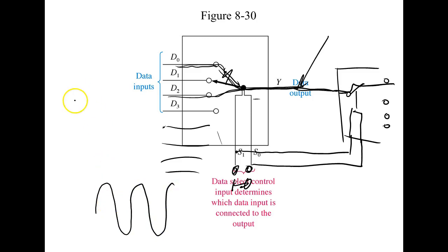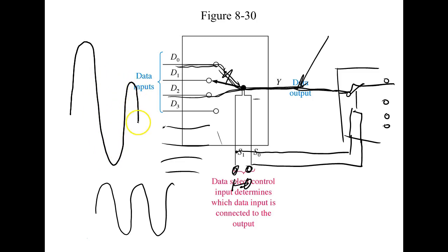And then I can do one of 2 things. I can take that carrier and I can change the amplitude. So if I send in a 1, it might be a high amplitude. If I send in a 0, it might be a low amplitude. Now on radio, we call this AM. Y'all know what AM stands for? Amplitude modulation. So the carrier's running at a constant frequency, and the sound is modulating the what? The amplitude.